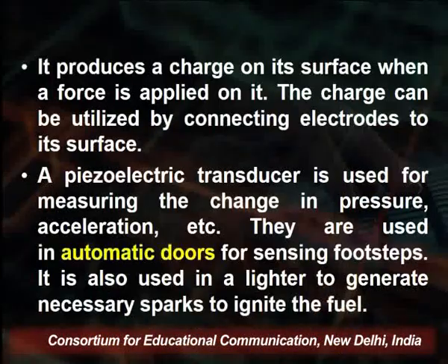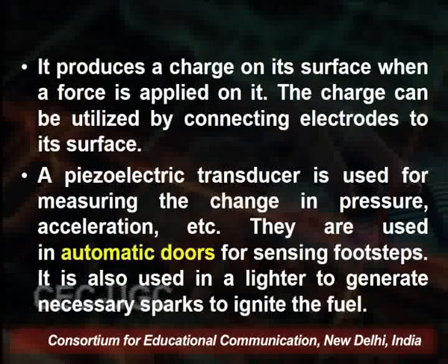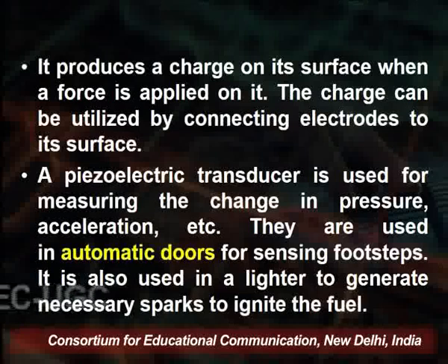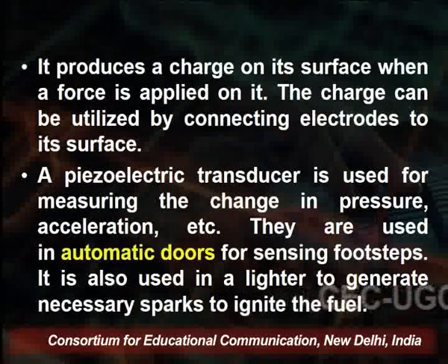Piezoelectric transducers are prepared by using quartz crystal. Plates are prepared, and it produces a charge on its surface when a force is applied on it, and that charge can be utilized by connecting electrodes to its surface. This measures the change in pressure, acceleration and so on. You see, on the basis of how much pressure we are giving, we will get the output signal. So the piezoelectric transducer is used for measuring the change in pressure, acceleration etc.